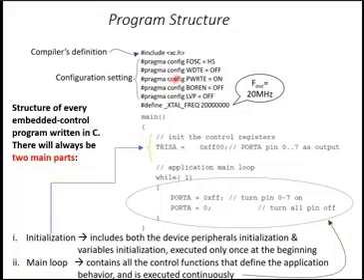This is followed by angle brackets, open and close. So the code must be the same, and it is also case sensitive. It is very case sensitive, so you need to follow it. Everything must be lowercase. And then after that, the configuration settings related to the microcontroller: frequency of the oscillator, what type of oscillator, watchdog timer, whether you want to enable or disable it, power on enable, brown out enable, and low voltage warning. These are the important items that you need to include.